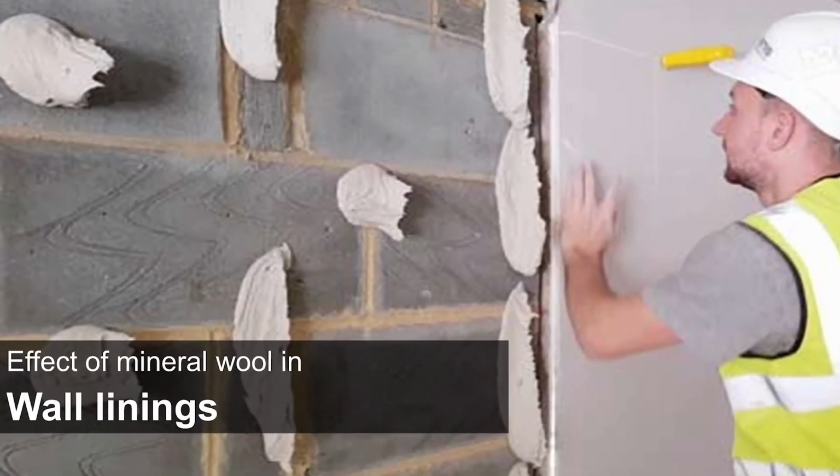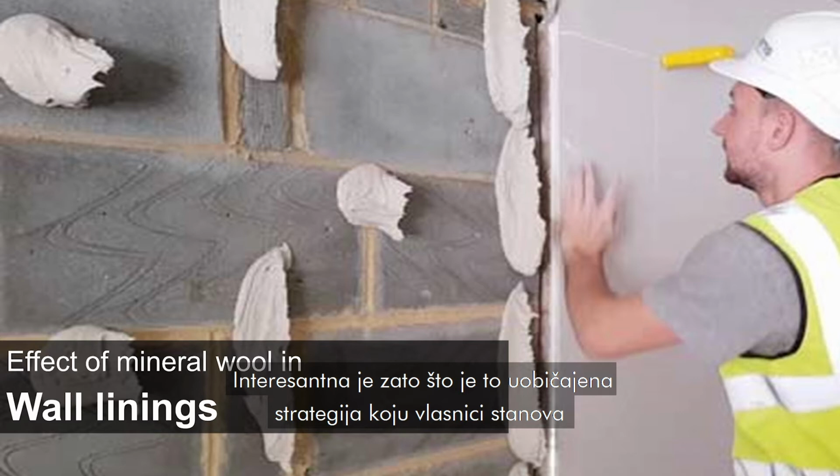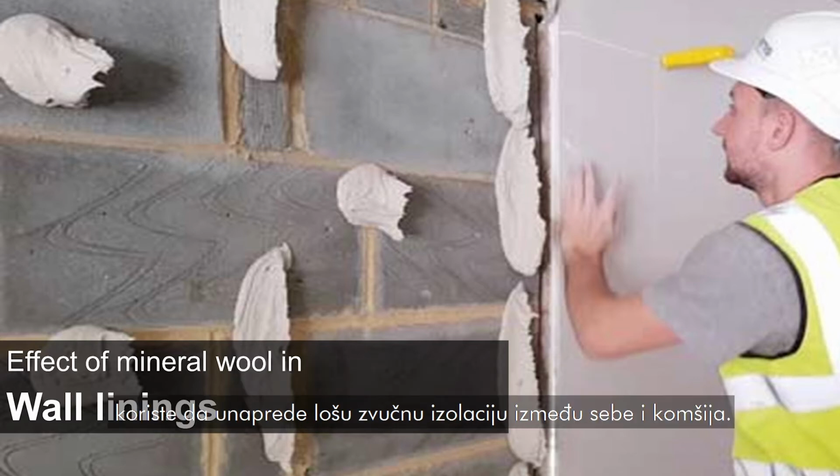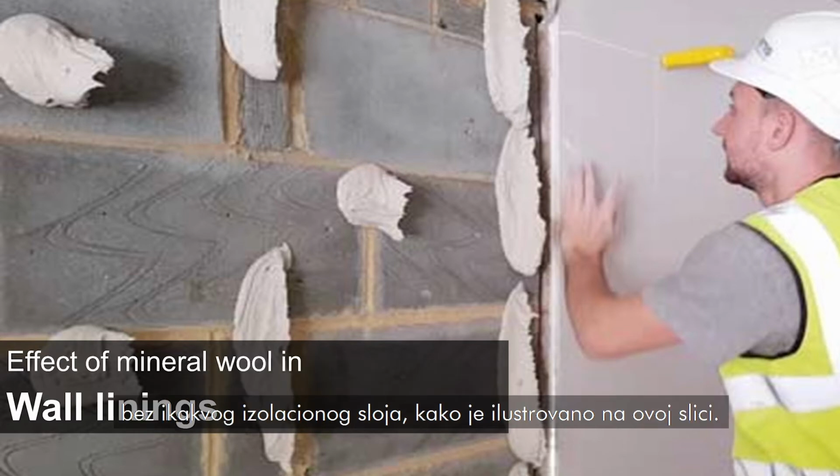When we talk about sound insulation, the wall linings are also a very interesting subject, because this is the strategy which homeowners utilize to increase the poor sound insulation between themselves and the noisy neighbors. And what we see as a very common technique is a direct fixation of the gypsum board to the main wall, as given in the image, without any insulating layer.